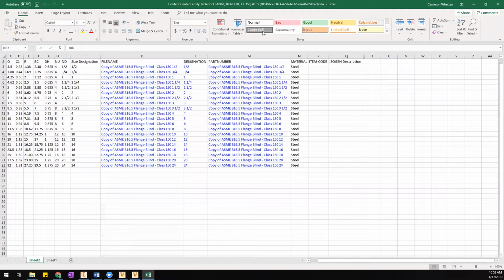So a lot of people had Excel 2016 and Inventor 2014 or 2015, and they could not access some of this stuff because they had an unsupported version of Excel. So just make sure that's something you check. There's a lot of people who say, oh, I don't have Excel installed, but my Inventor's working. Well, Inventor installs a portion that it needs to function. If you have a full version of Excel installed, it needs to be a supported one. If you don't have Excel installed, period, Inventor will install a widget that's big enough to do some of this stuff. So just FYI. Cool. Thanks, Nigel.